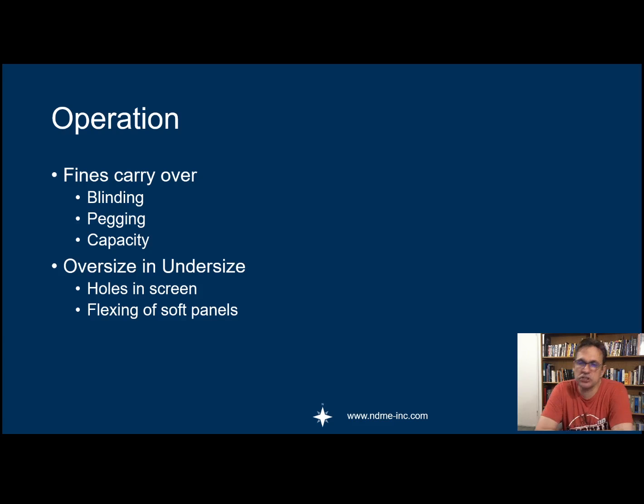Now in operation you also get fines carry over, and that's basically where fine material gets stuck in the oversized material and hasn't got a chance to stratify through to the screen panel, and you've got fines actually carrying over into your oversize. And it's also exacerbated often by blinding and pegging, and you can do the solutions that we discussed previously.